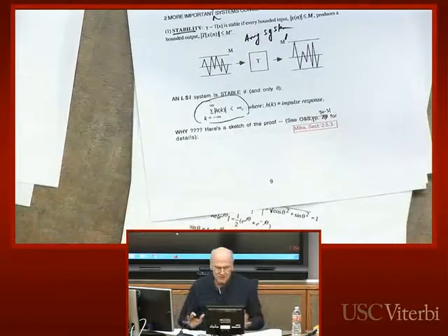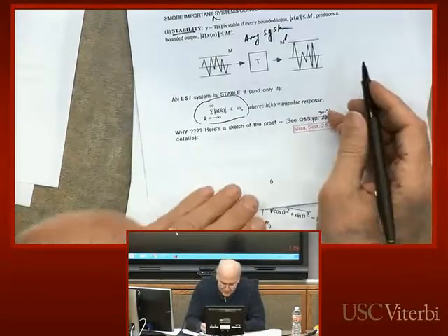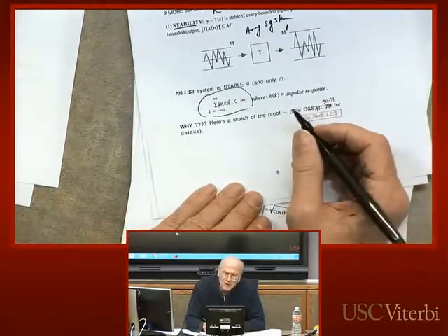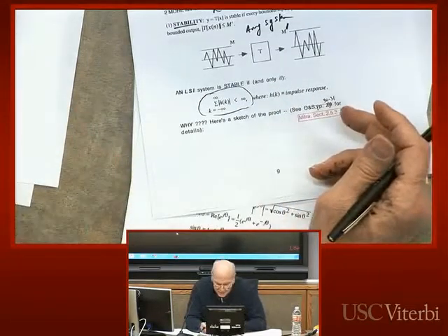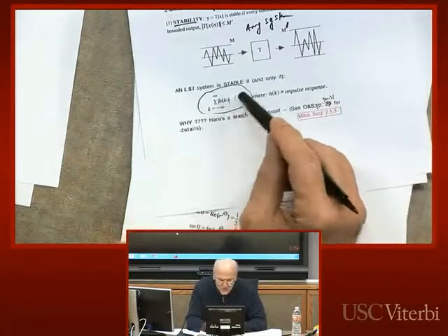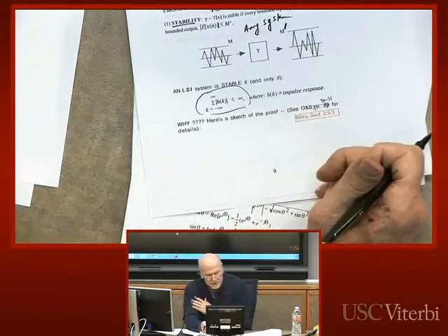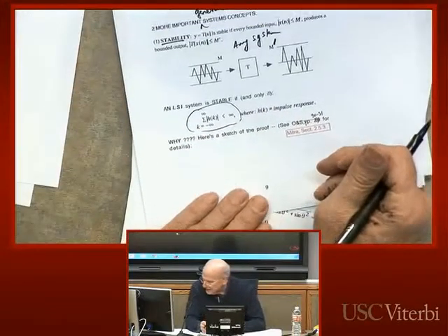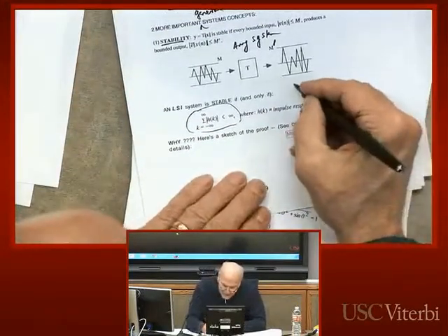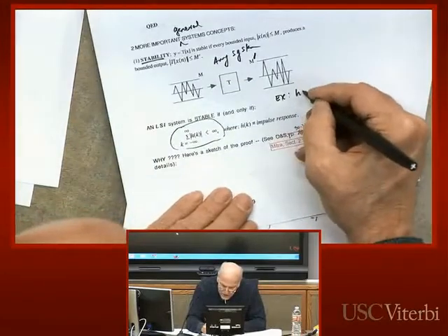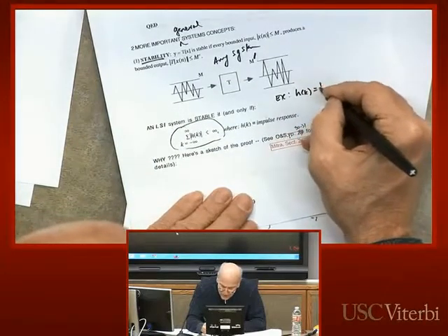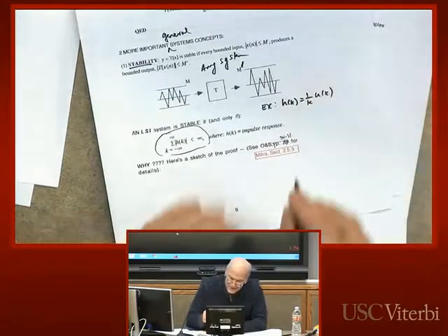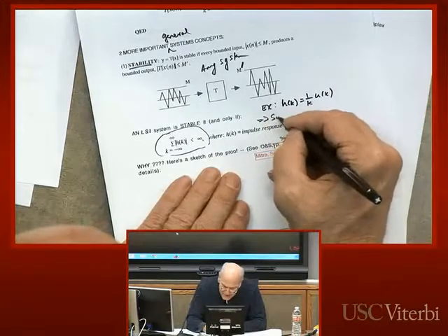So again, for linear shift invariant systems, everything goes back to the impulse response. Namely, the impulse response has to be absolutely summable. In other words, the sum from minus infinity of the absolute value of the impulse response has to be bounded. As an aside, if h of k is equal to 1 over k times u of k, it turns out the system is not stable.